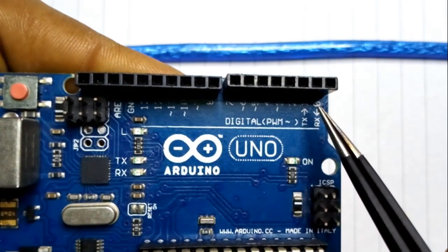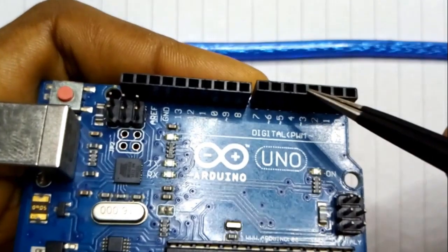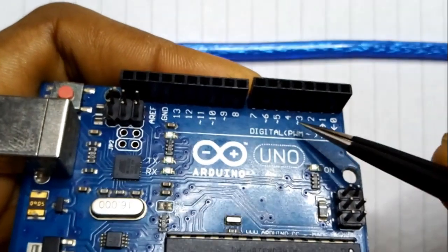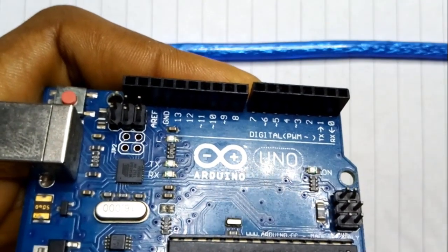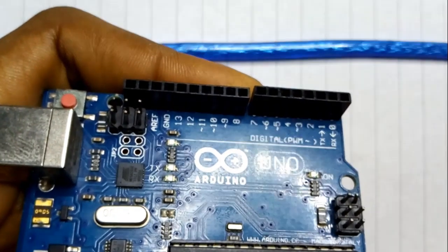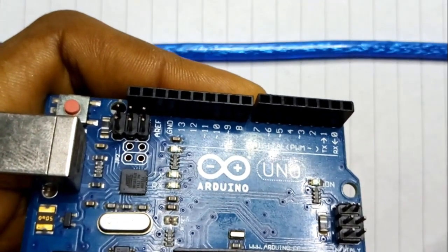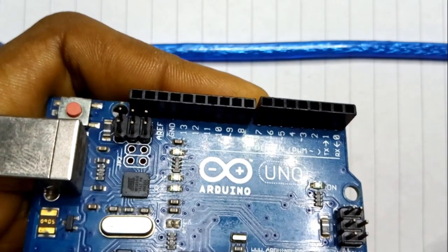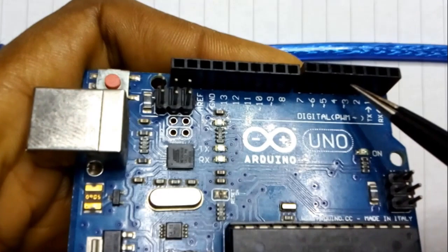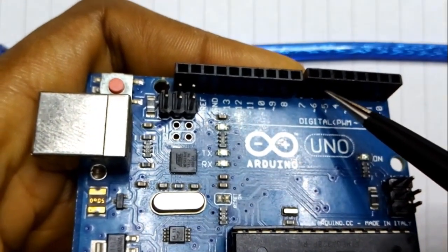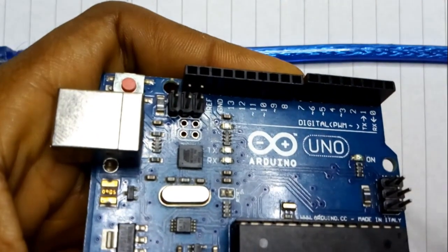or the TX pin. Digital pins 2 and 3, as the label shows, are capable of external interrupt. Interrupt basically is a way of suspending the microcontroller's current execution to do something else for a brief moment of time. 6 digital pins, digital pin 3, 5, 6, 9, 10, 11 are capable of what we call